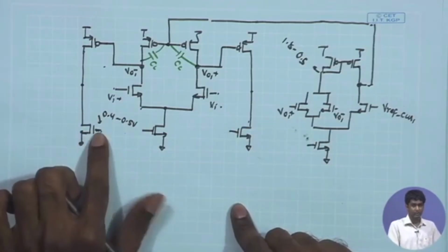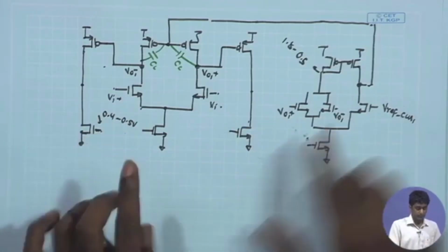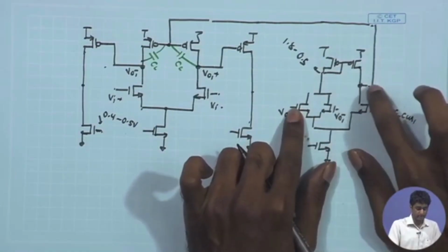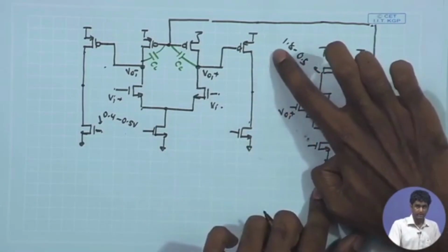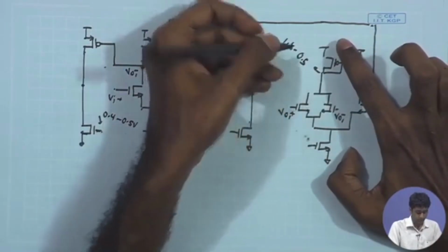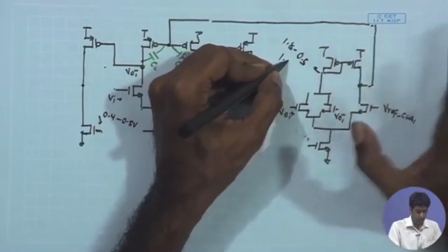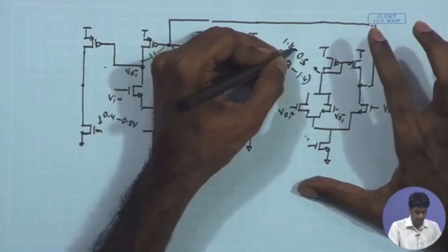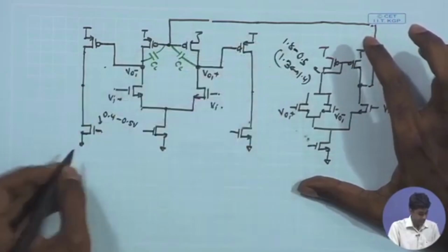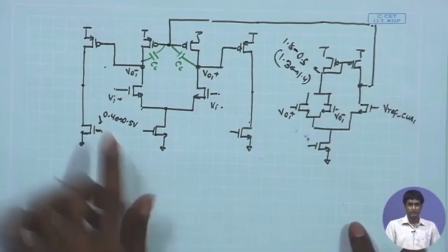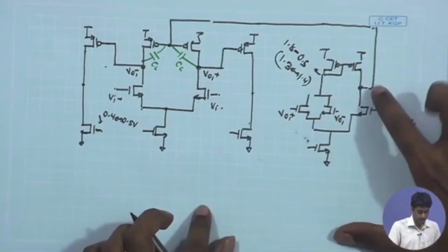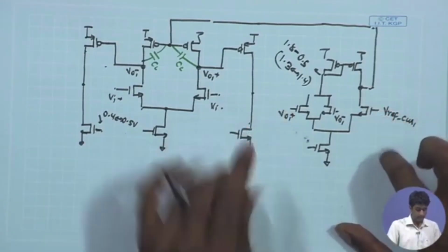This is what we expect over here. So, if I look at the DC condition for this amplifier, nominally this potential will be in this range, 1.8 minus 0.5, so around 1.3; it can go to 1.4 in this range. So, this is a minus sign and this is the range. Just let me distinguish this. So, this is also, I am talking about the range 0.4 to 0.5 volt around,